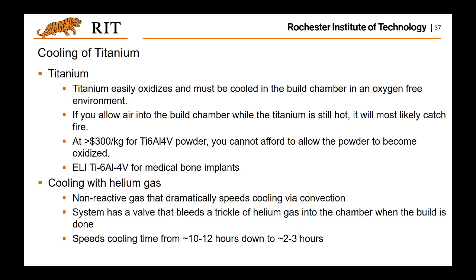And usually the cooling happens with helium gas. The helium gas will not have a chemical reaction with the titanium, the powders, and the part, so that will make sure no oxidation happens.